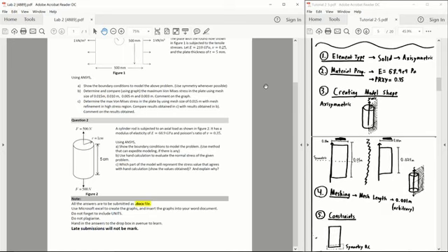Next, we can go ahead and determine what element type we will use in this question. Our best bet for this model would be to use a solid element type with an axisymmetric function defined. Basically, what axisymmetric will do is it will revolve your model around the y-axis.